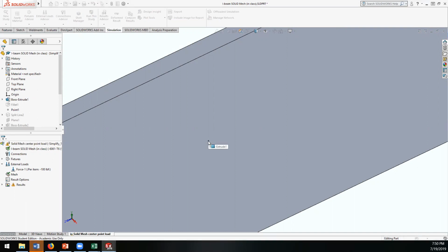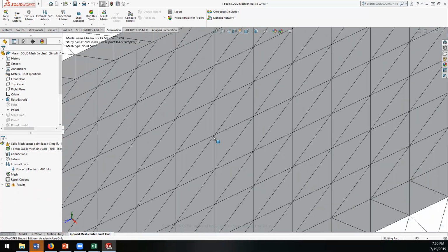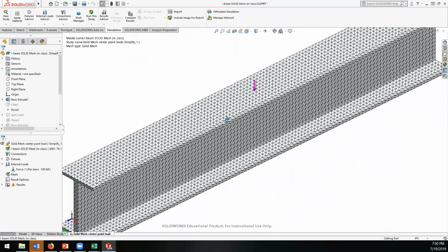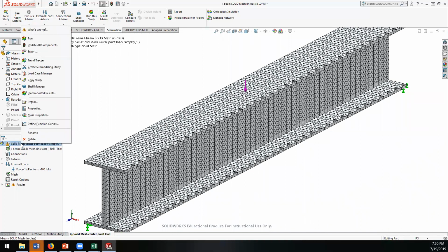If you didn't take statics or strength of materials, mostly statics, you probably would have thought the high stress point would be at that restraint. You might run it once and get that result, and that's not where the high stress point should be. It doesn't mean FEA is wrong. It means your model is set up wrong.